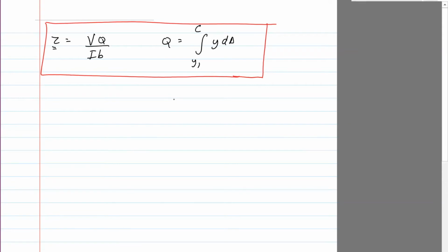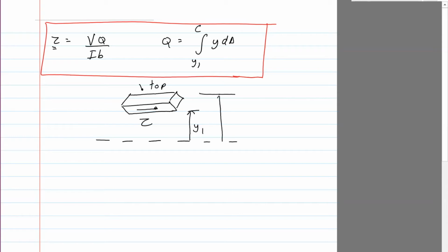Once again, this is the shear stress if you have a small element and you look at the bottom face. So that's the top, that's the bottom, and that's where the shear force acts. This assumes a small element of the beam as I showed earlier, and say this is the neutral axis. Then this bottom section is at a distance of y1, and the top section is at a distance c. We used a different notation earlier; I think we used y max for c.